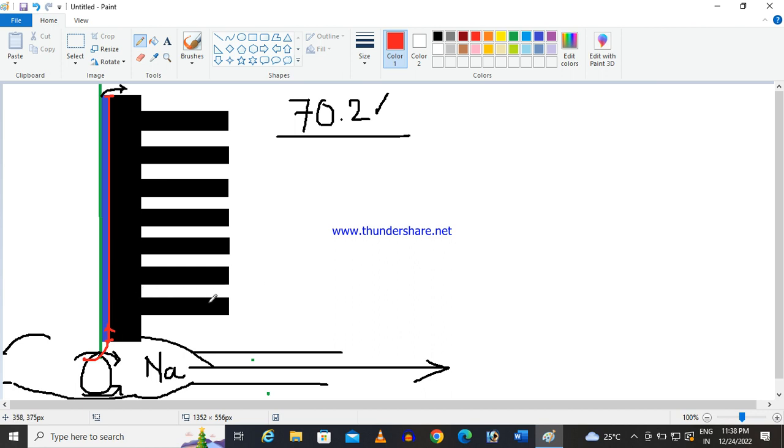If sufficient heat can be evacuated from the sodium rising through the annular path, and before reaching the gland the temperature of the sodium comes down below some 96 or 98 degrees Celsius, around 90 degrees, then the sodium itself will freeze, and by freezing it will be perfectly leak tight.